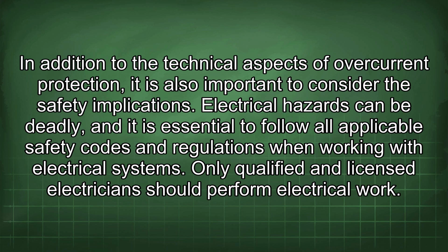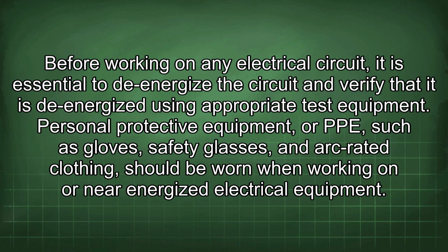In addition to the technical aspects of overcurrent protection, it is also important to consider the safety implications. Electrical hazards can be deadly, and it is essential to follow all applicable safety codes and regulations when working with electrical systems. Only qualified and licensed electricians should perform electrical work. Before working on any electrical circuit, it is essential to de-energize the circuit and verify that it is de-energized using appropriate test equipment. Personal protective equipment, or PPE, such as gloves, safety glasses, and arc-rated clothing, should be worn when working on or near energized electrical equipment.